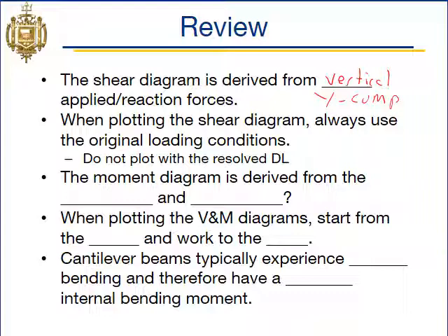All right, big one here. When plotting that shear diagram, always use the original loading condition. If you have a distributed load, go ahead and put that distributed load back on. Do not plot it with your resolved distributed load, that one point load you made to do your moment equation. Get rid of that and then put your distributed load back on to do your shear and moment diagram plot.